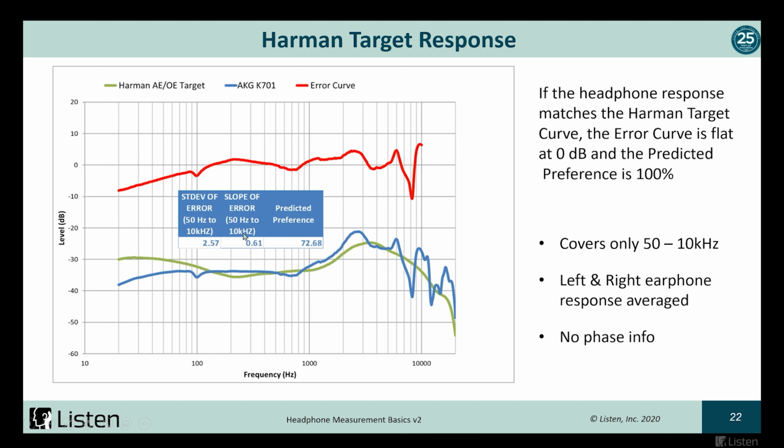And they don't take phase into account, which is another controversial thing. I actually think phase does matter. And if you ever attend my high-res headphone presentation, I will explain why phase matters at high frequencies, because it actually impacts the phase at the lower frequencies. Not that people can hear above 20 kilohertz, but there have been subjective listening tests that show with headphones and the right kind of music, actually around 2 to 4 kilohertz phase does matter considerably.